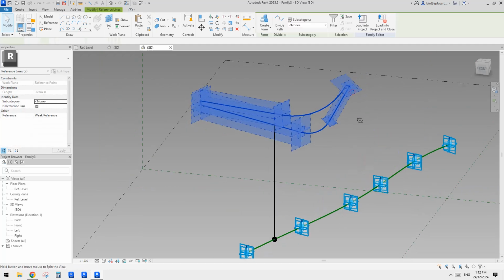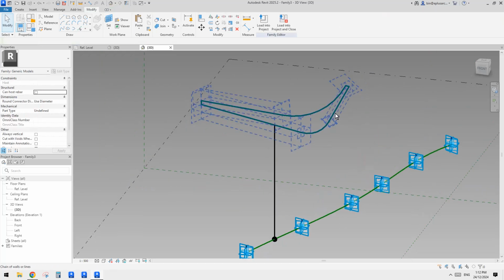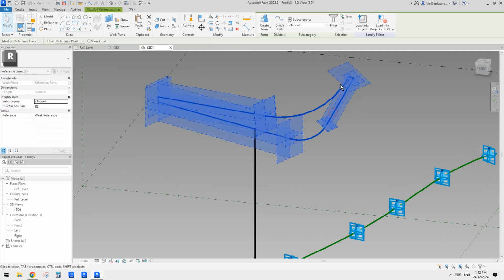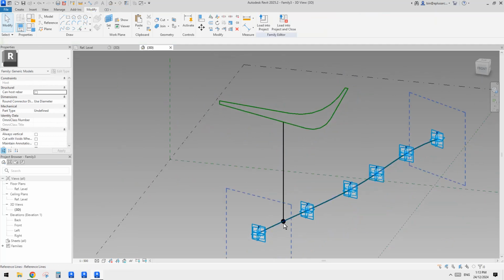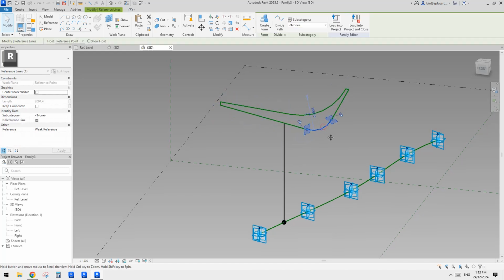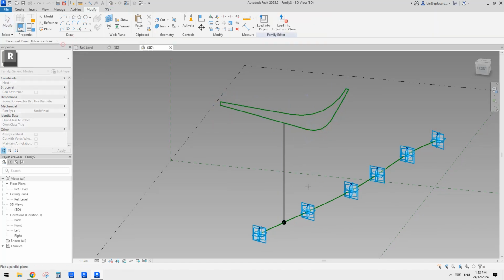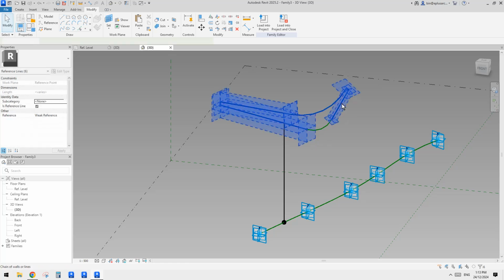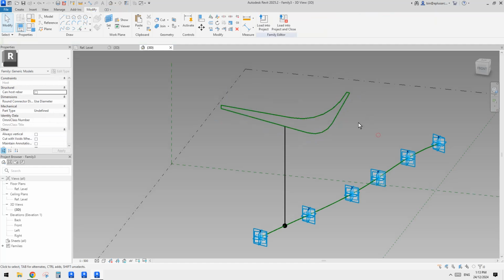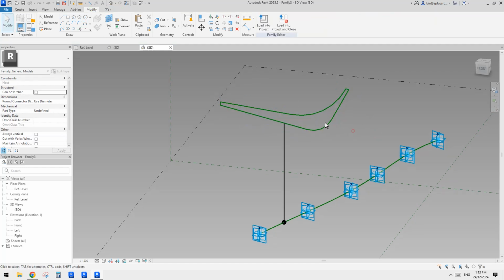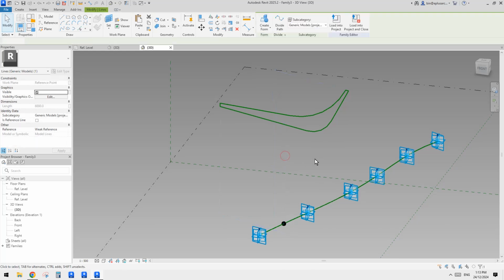So now we can see when I move my cursor onto the reference line, it will automatically pick all these lines. Reference lines means all these reference lines are on same work plan. Okay, so if one of them, so for example this one, if I pick something else, pick on this reference line, for example. So now when I try to select, it will not include this line. Okay, so let me just Control Z, make sure, all good, and then we don't need this line anymore.